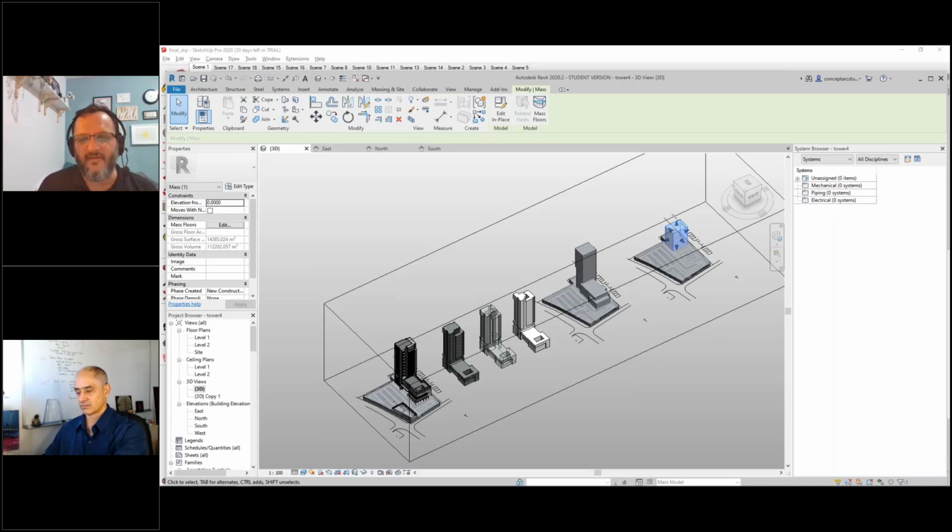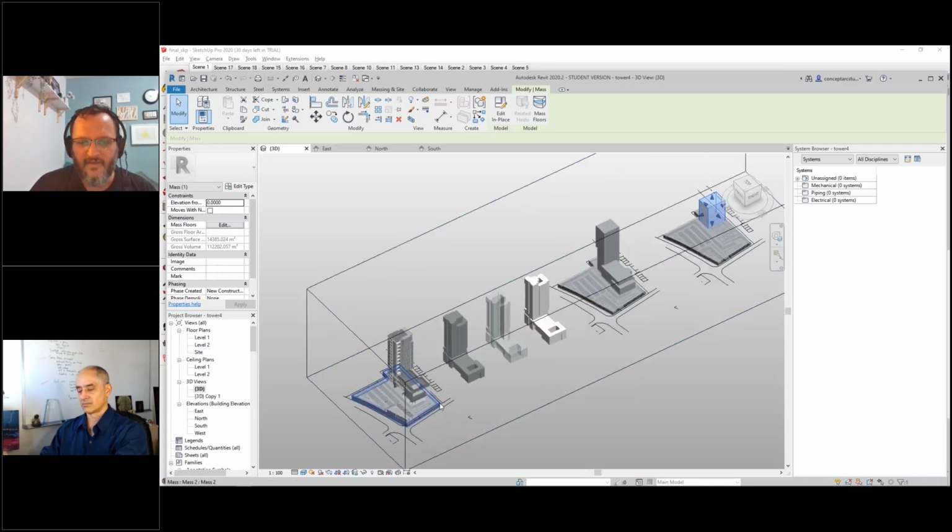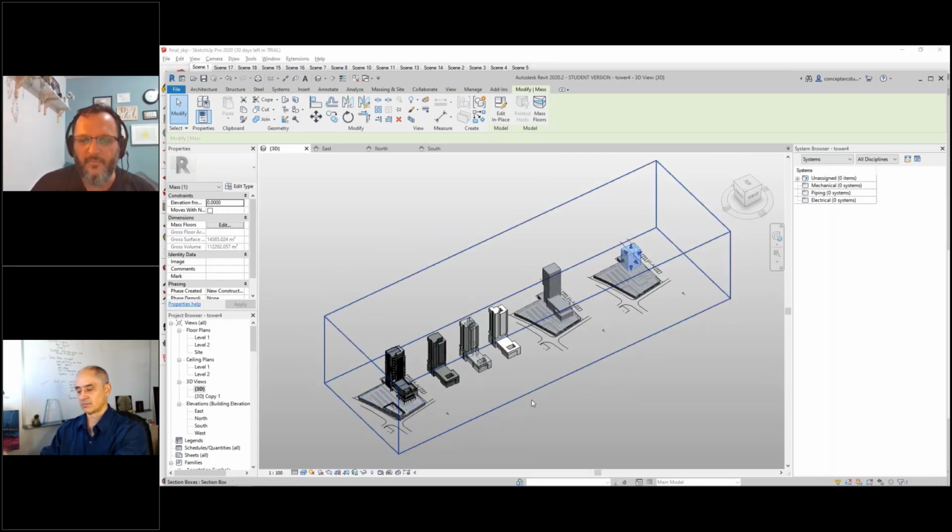But then I come back into Revit and continuously model in my Revit package, because at the end of the day, the Revit model is very clean and crisp. Also, if you do adjustments in SketchUp, they won't be so huge. They'll take 2 or 3 minutes to add to your Revit model instead of hours.